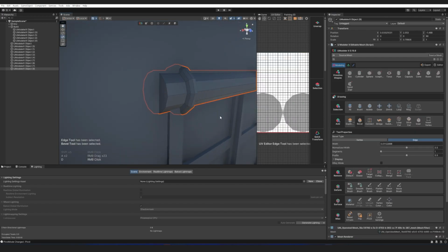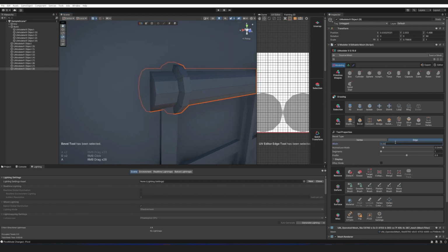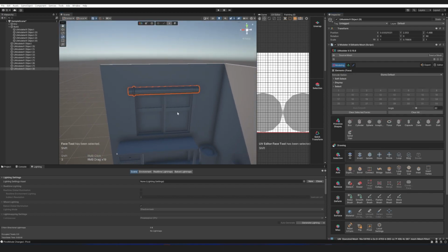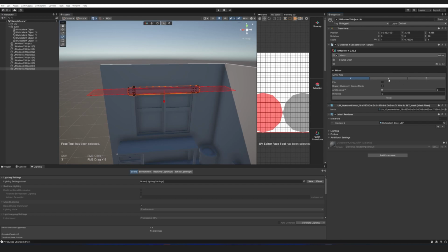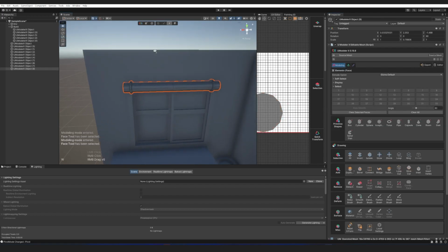Create the same shape on the right side as well. When creating symmetrical objects, use the modifier function for easy creation. Next, I will introduce the mirror modifier function. Click the plus button in the right window to find the mirror button in the submenu. The mirror function transforms objects by mirroring them along the X, Y, or Z axes.